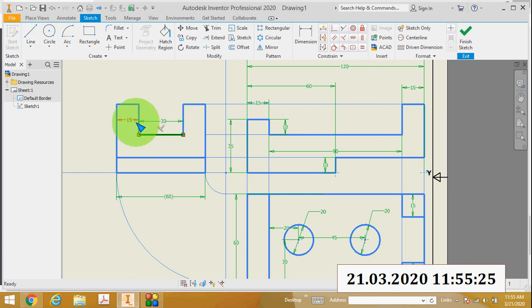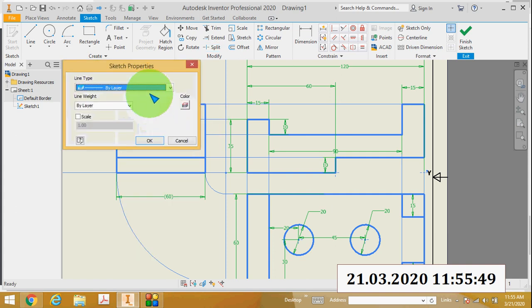So before that I will delete this dimension for viewing. Okay, so I just project this. Okay, so you can see this edge. Some portion you can see, some portion is actually invisible. Okay, so visible you just draw using dark lines. So this is the visible edge.